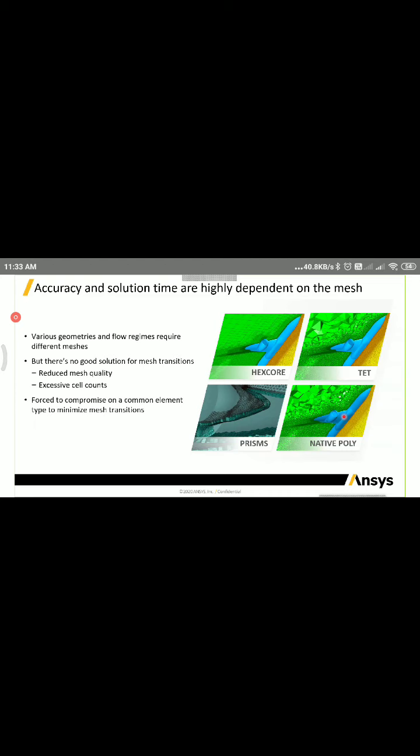So it depends on which particular algorithms we are going to use, how they are going to capture your geometry, whether you have properly captured the prism layer requirement to capture the boundary layer phenomena near walls, and the density in the wake region or where the shocks are coming, whether you have the proper density to capture such phenomena.